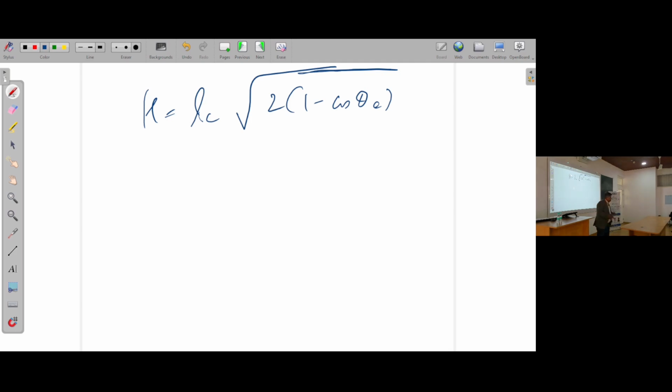That is the answer. It is basically dependent on the capillary length corrected by some factor corresponding to the contact angle. So we don't have to do anything else. It's a very quick way of estimating the height of the film, especially, and we use this constantly in various things as a first guess of what the answer could be. So this is one of the elements I wanted to explain regarding capillary length.